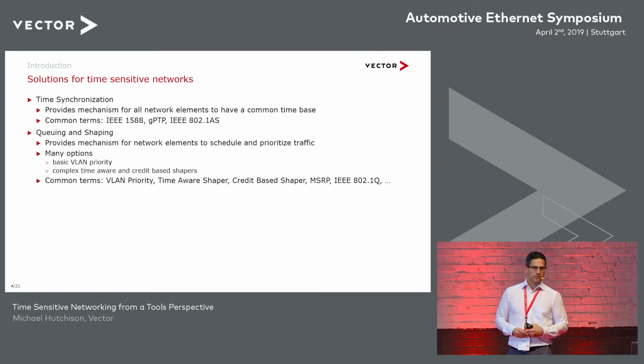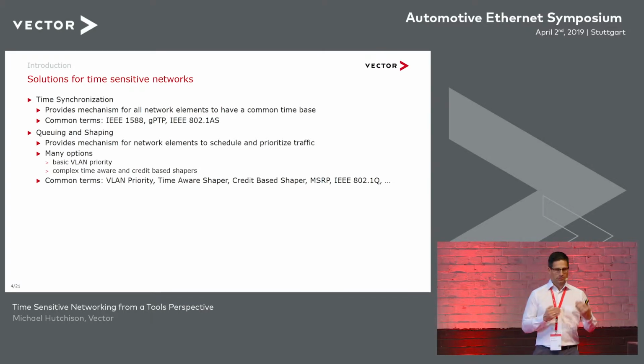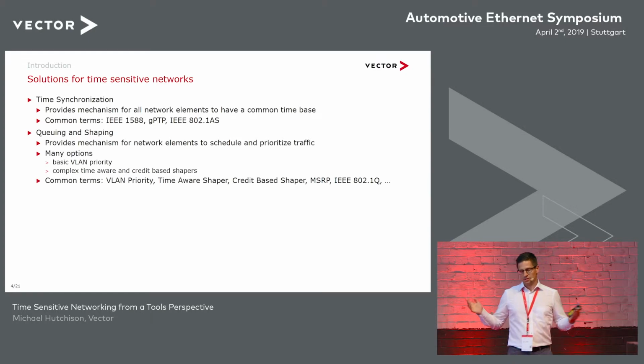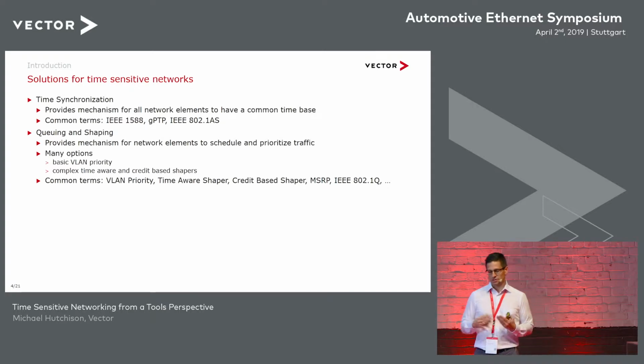Within the standards and the technologies that we see, I'd really try and divide things into 2 areas. The first one I think of is time synchronization. So in order for anything to happen, we really need all the elements in the network to have a common understanding of time and a common time base. And that's where time synchronization comes in. So if you're hearing terms like IEEE 1588 or gPTP or IEEE 802.1AS, we're generally talking just about synchronizing time in a network.